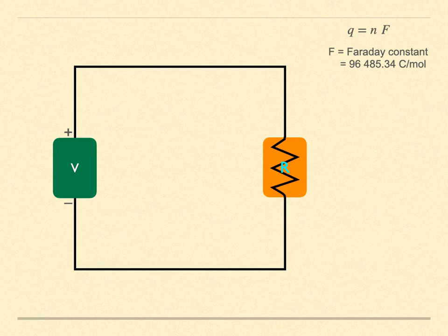In an electric circuit, as long as the resistance is not infinite, there is a continuous flow of charge from high to low potential energy. This flow is called a current. In a circuit such as the one shown here with just a single path, the current must be the same everywhere at the same time. If not, charge would be building up somewhere and decreasing elsewhere. The conservation of charge requires that the current be the same everywhere. Current is measured in units of amperes and is the amount of charge in coulombs passing a point in the circuit per second. Now here's the relationship.